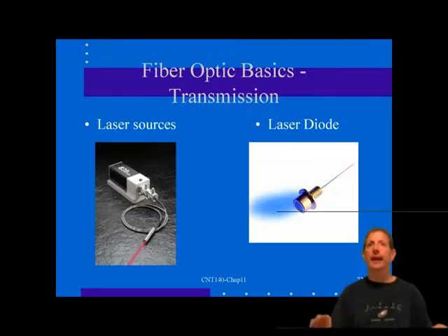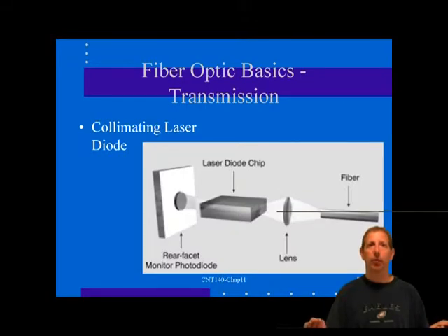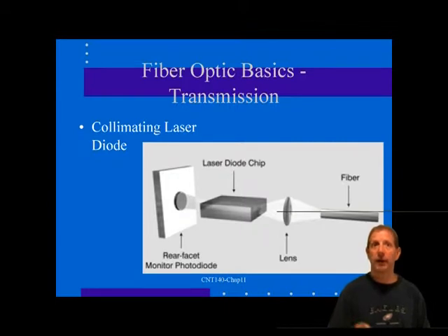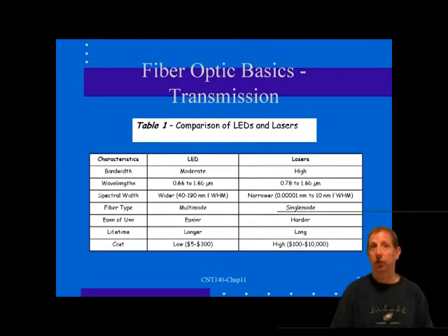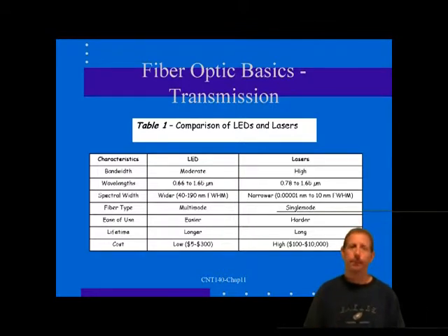At the end of the cable, the outer jacket and strength layers are removed. Any filler or central structural members are cut and discarded. The tubes are then carefully cut to an appropriate length for terminating, and the individual fibers are prepared for and terminated in the appropriate connectors. Strain relief, fiber routing, and excess fiber storage are provided in the fiber termination tray.